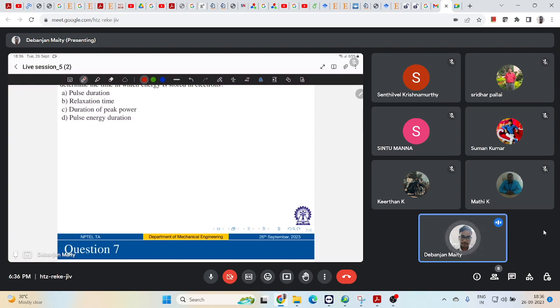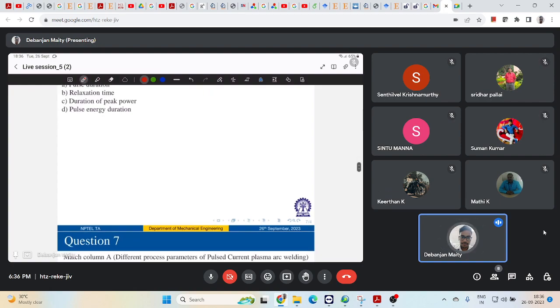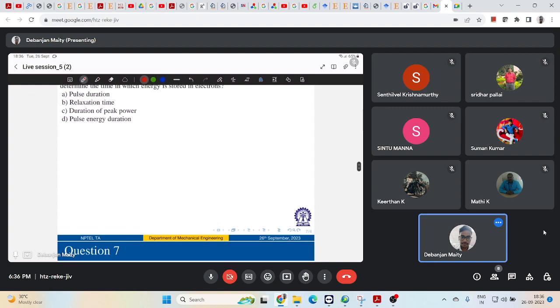And if you see in ultrasonic welding, it can be characterized mostly by a small rise in temperature. The temperature rise will be very less. So, what are the materials this is generally used for? This is mostly used for plastics, especially for joining very thin sheet metals, maybe 300 micron, 500 micron. It can be used for dissimilar materials also. And the electronic industry mostly uses ultrasonic welding or resistance spot welding, right?